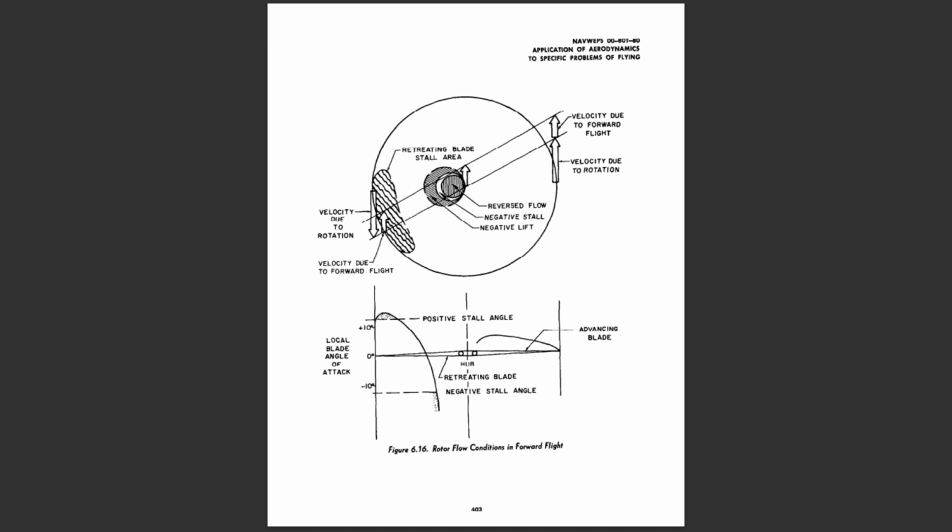Juan de la Cierva was the first to realize what caused this effect, and he solved the problem by mounting his autogyro blades individually on flapping hinges, thus allowing a flapping action to automatically correct the dissymmetry of lift that resulted from forward flight. This is the method still used in an articulated rotor system today.